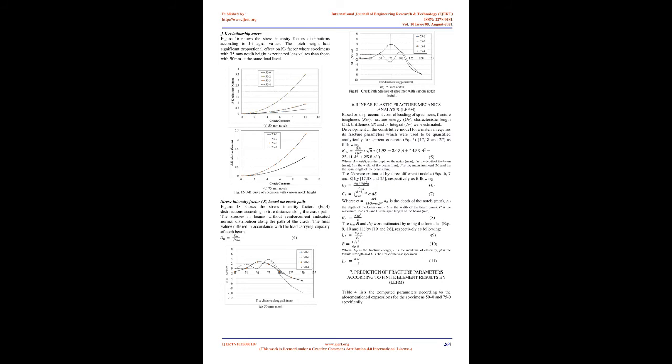It can be observed that for the FGPC specimens, without reinforcement, increasing the notch height decreased the load carrying capacity by 64%. The presence of reinforcement improved, as expected, the flexural capacity compared with the FGPC beams without reinforcement by 30% and 35% for 3 and 4 mm rebar diameter respectively.